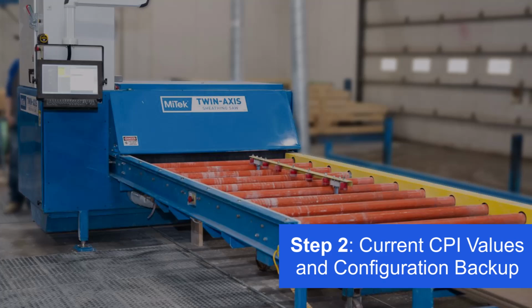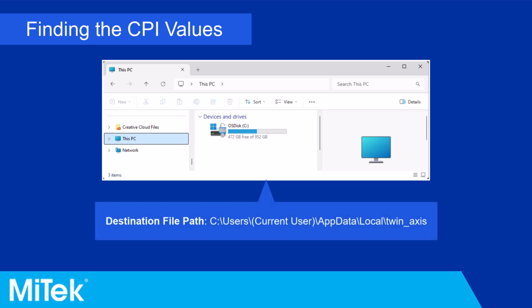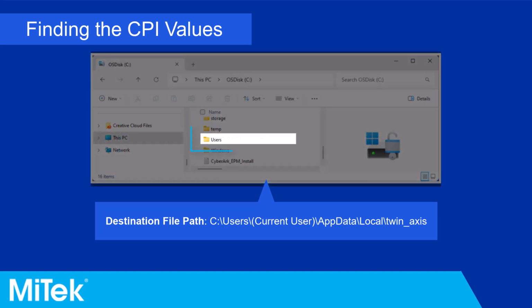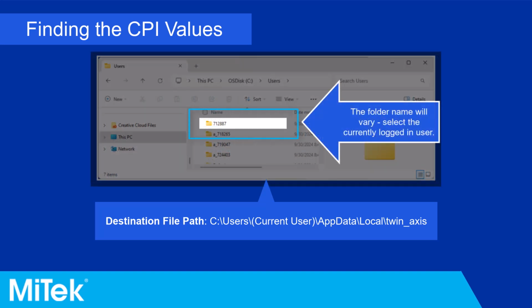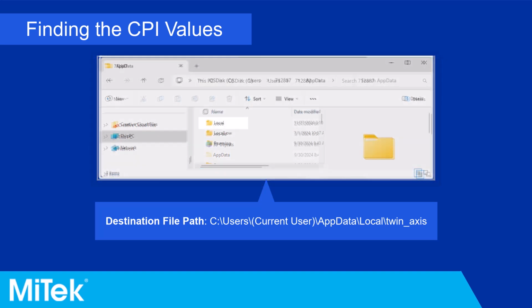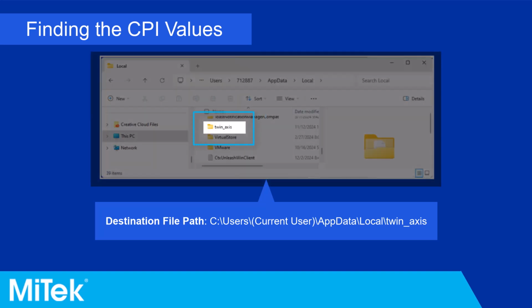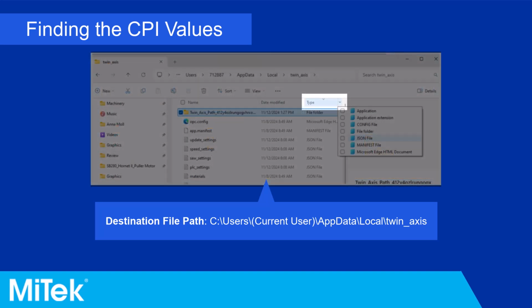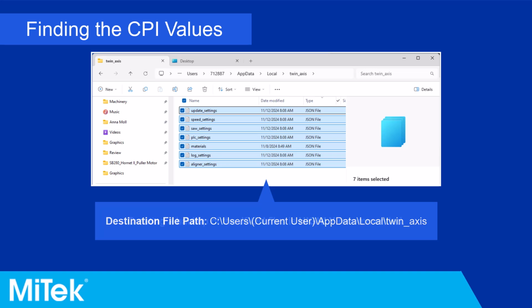To find the current counts per inch value, start by navigating to the C drive on the computer. Open the File Explorer, navigate to C drive and open it. Open the Users folder, then open the folder of the logged-in user. Open App Data folder. Open Local. Then navigate to and open Twin Axis. At the top of the File Explorer, click on the small arrow drop-down next to Type and select JSON. This will display only the JSON files.